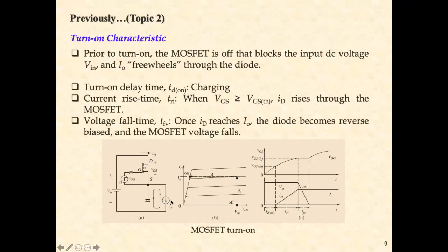Later, especially in the second half of the subject, you need to pay attention to the loading. Sometimes it is open, sometimes it is with a constant current source, and sometimes it's with a resistor, and so on. So you just need to read the topology very carefully. And then this is the turn-on characteristics waveform for VGS, drain current, and VDS.